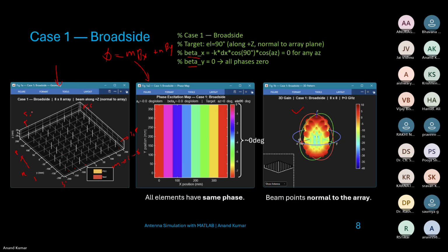Okay, so we'll have a mesh, and m and n will give the location of the dipole, and beta x and beta y will give the phase based on the tilt that we want, and this phase will be then given to each dipole. So from this combination, we'll have the phase for each dipole at phi m comma n.